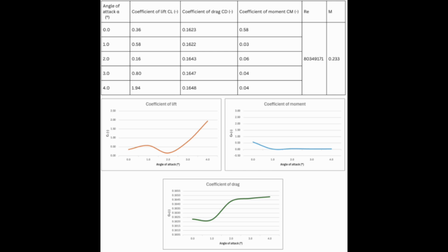This makes sense because as the angle of attack increases, the curvature of the airfoil relative to the free stream is larger, which, according to the circulation theory, would increase the disparity in speeds on the upper and lower surfaces.